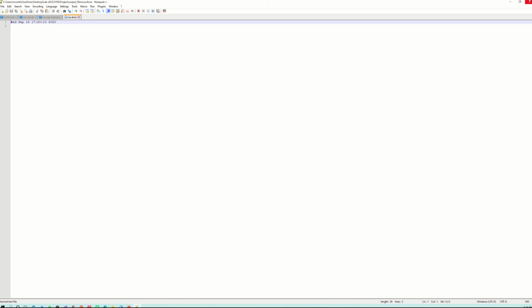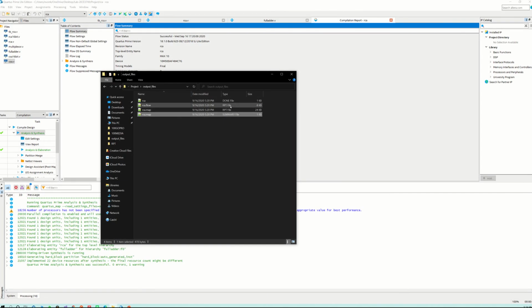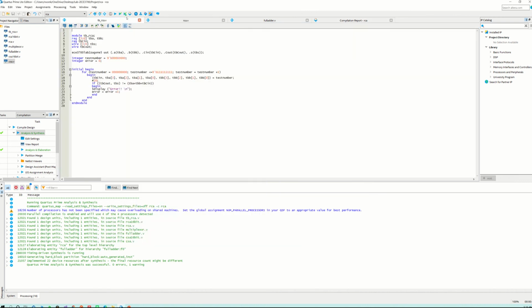To have a much cleaner picture about all this, it is better to open these reports after you assign pins and perform compile design completely, and then you'll have better reports that are more reliable than what you saw just now. So these reports give you a rough idea as to how your design will fit or what the size of your design is on your board. So go through those reports, see where the area numbers are, see where the delay numbers are, and try to analyze how things work. And the same thing should apply for the other adder modules as well.